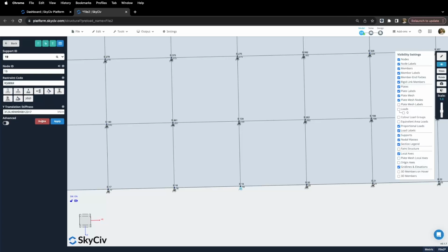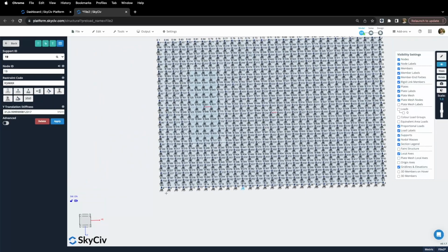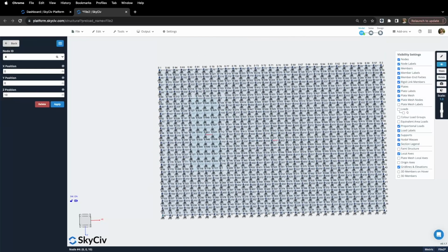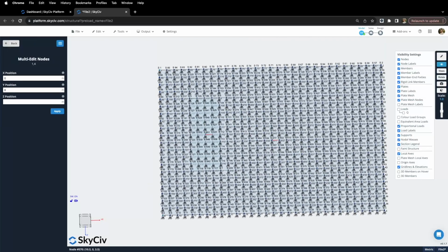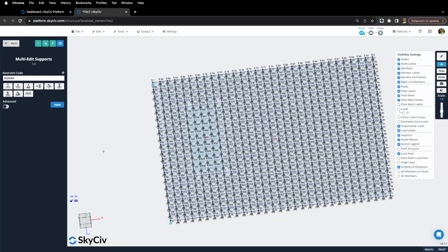3,125 kilonewtons per meter. So the other thing I need to apply is I need to apply some lateral restraints for stability of the model. Now, if you were concerned about lateral loads on this slab at all, say something causing sliding on it, you might want to model in a spring support for the lateral direction as well. Again, you could get that from a geotech or use your engineering judgment.